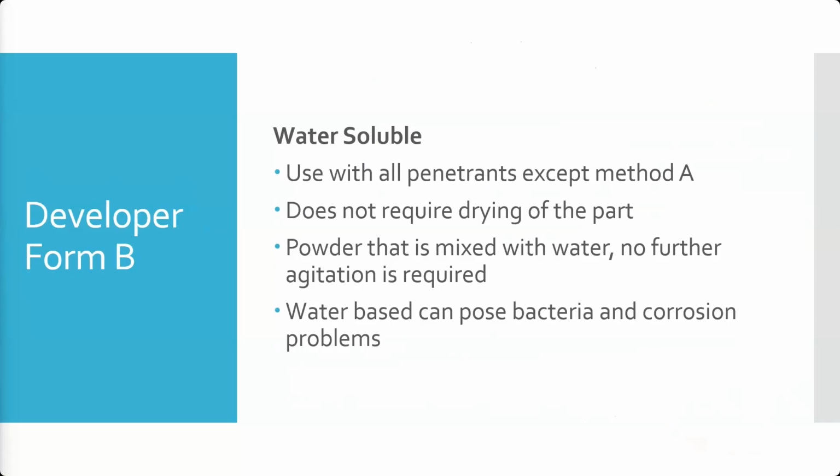It turns that water into a solution, and when you put that water over the part, the water evaporates, leaving behind the developer that was dissolved in it. It's like if you take salt water and it evaporates, it leaves behind salt crystals on whatever that was in, right? Or sugar crystals if you ever made crystals growing up. Or the salt that ends up all over your car in the winter in Michigan and then causes it to rust out. So it leaves that behind, used with all penetrants except method A.